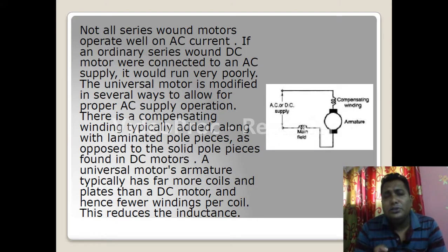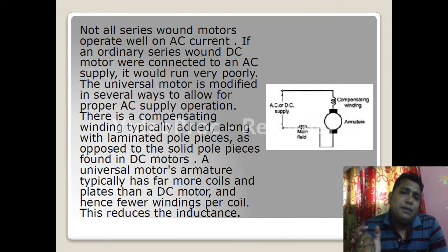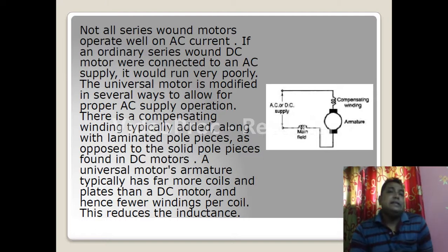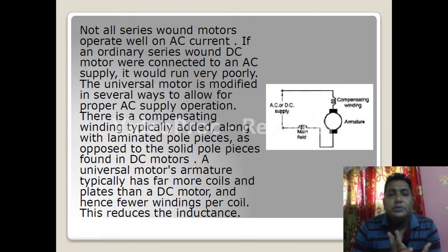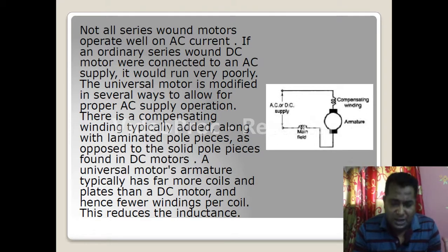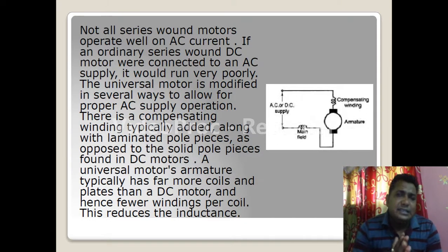when we want to use that motor as an AC motor? We use a lesser number of windings, but here we use thick wires. Lesser turns of winding means lesser length of winding, and lesser length of winding means a lesser amount of resistance and reactance inside it.